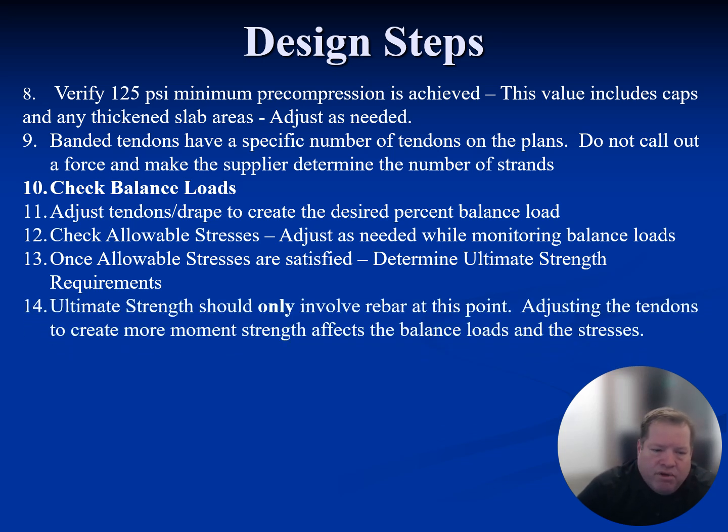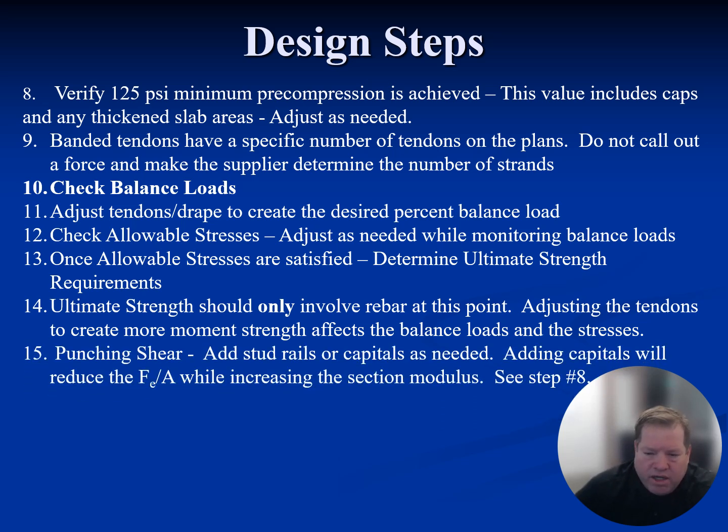Once you've designed for allowable stresses, the ultimate strength should only involve rebar at this point. Whenever you change the number of strands, the force, or the drape, that affects the stresses. So you have to go back to the previous stress design and do that. So again, once the stresses are satisfied, PT is done. Now we're just checking rebar.